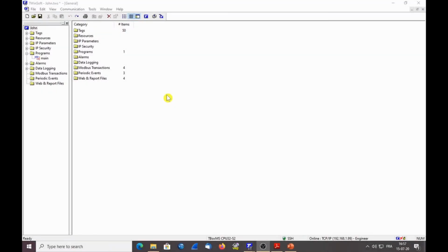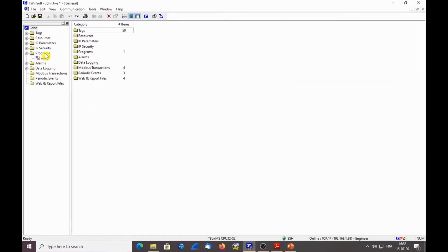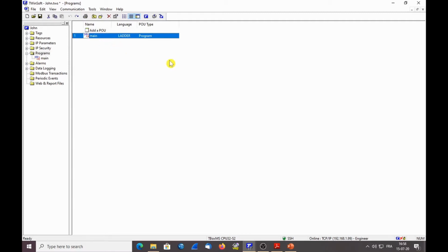In this video, we will cover the PLC programming. PLC programming is required when you have to handle a process. And remember, our process is a pump with a water tower and 3 networks with valves. In TwinSoft, you will define the PLC programming in the folder Programs. When you open Programs, you see we have one program called Main, in which all our process will be called.